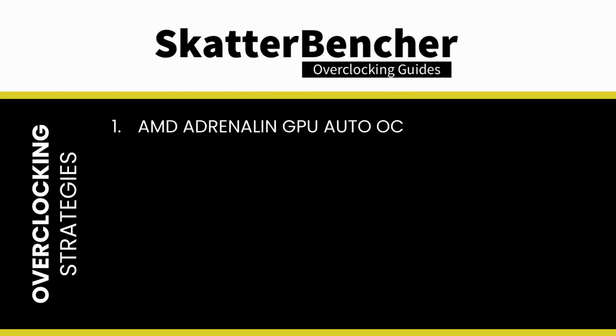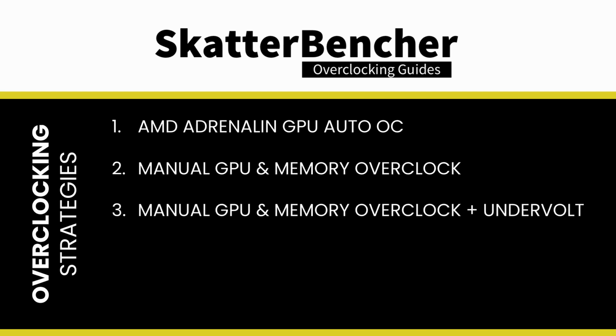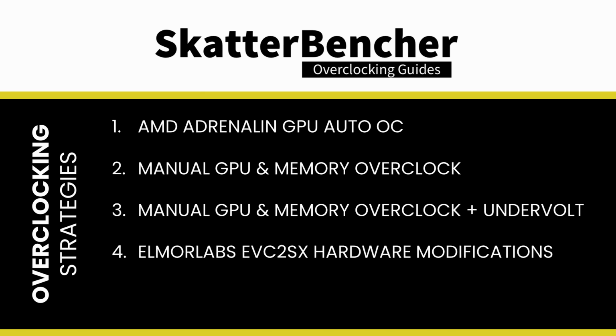In today's video, we will cover 5 different overclocking strategies. First, increase the GPU frequency using AMD's automatic overclocking feature. Second, we manually increase the GPU and memory frequency with the AMD Adrenalin tuning toolset. Third, we try to use the undervolting tool to increase the GPU frequency further. Fourth, we use the ElmorLabs EVC2SX to work around some performance limiting issues. Lastly, we slap on a water block to get the most performance out of our GPU.